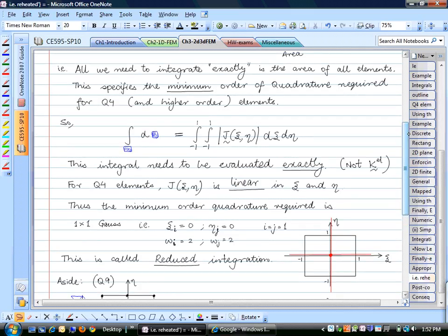But you will see, just like in this bending problem that I gave you, you started out with 10 elements, you went to 40 elements, 160, 640, 2000 something elements, and the change between 640 to 2000 elements was not that much. So it's a little bit of a judgment call when you say how small an element you need.